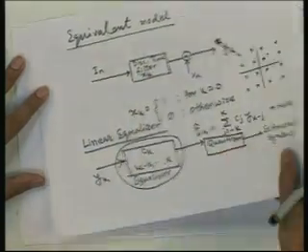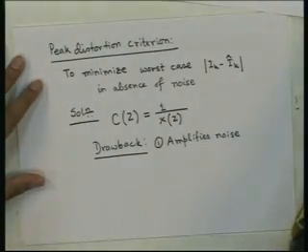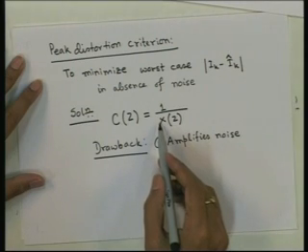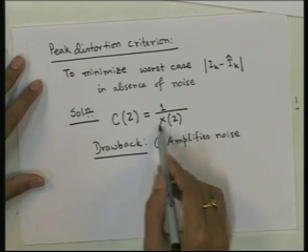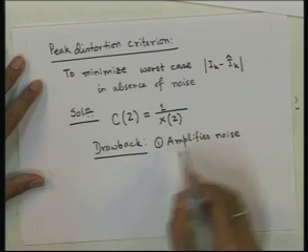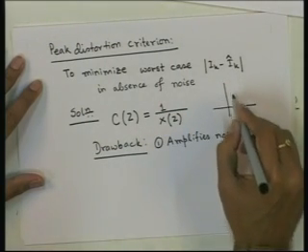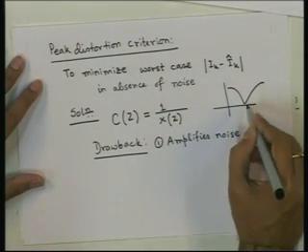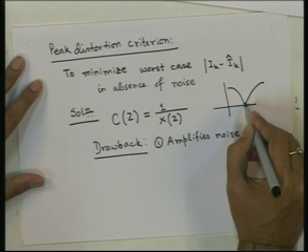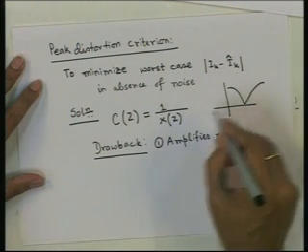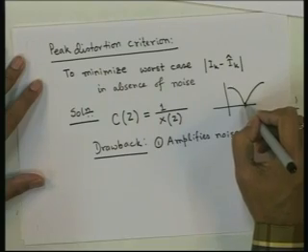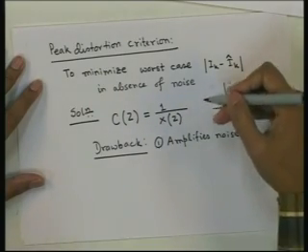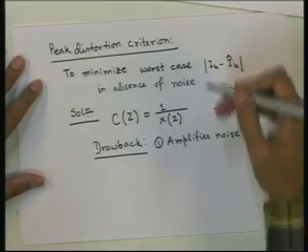So, if you consider the frequency response of this filter X z, and it has, let us say, some very high attenuation here, then C z will have very high gain at this frequency, because it is just the inverse filter of this filter.